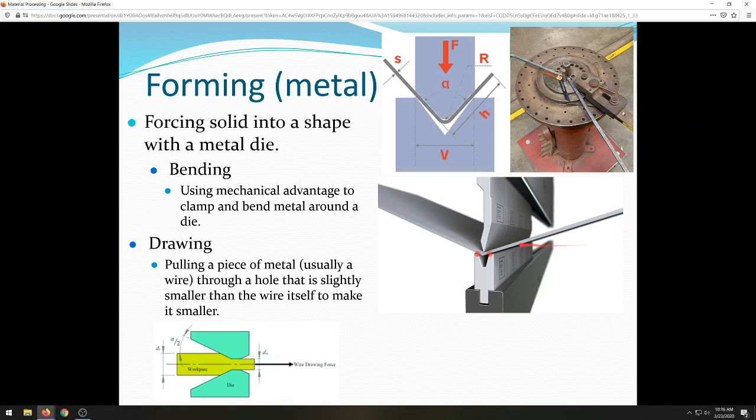You could buy an automated machine called a press brake, like this one, which has hydraulic rams that push this bending finger up and down, with different dies and things like that, and they can cost hundreds of thousands of dollars if they're computer automated or huge. Because you can bend 1-inch thick steel and aluminum with a tool like this if it's large enough.